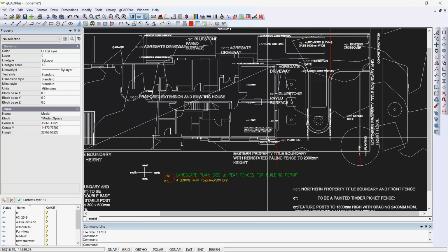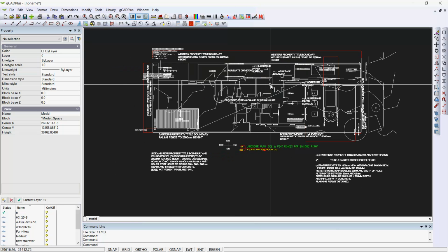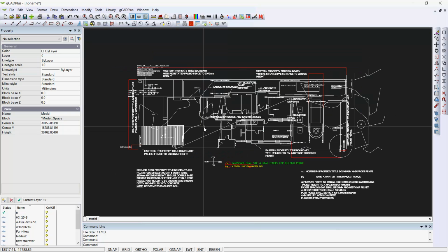So we've taken a drawing which was 7 megabytes, 7,000 kilobytes in DXF file, brought it down with a little bit of attention to blocks to 1 megabyte or 1,000 kilobytes, and then we're now to 117 kilobytes. I think you can see we have a very fast loading and very easy drawing now to work with. I'd be inclined to make that as a block, and just in case we need to go back through that process again, leave it as a block, and then put your landscape design on top of the block. Hopefully that shows you some of the problems you will grapple with when you accept drawings from foreign sources.